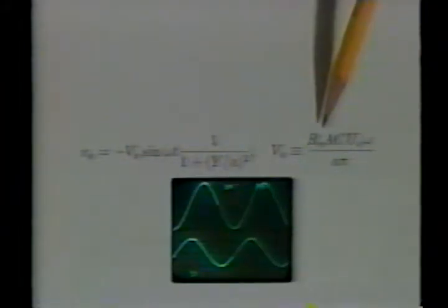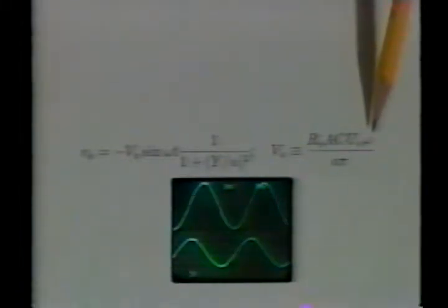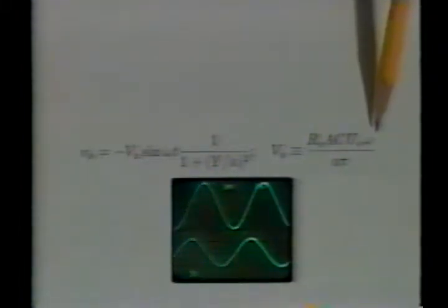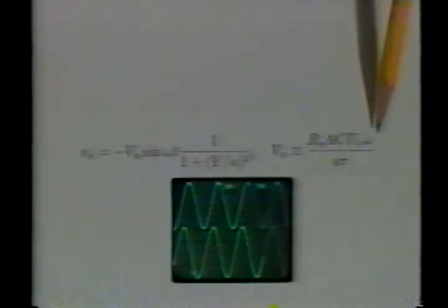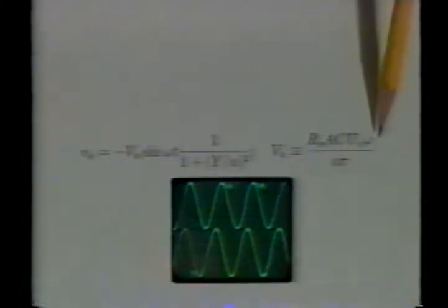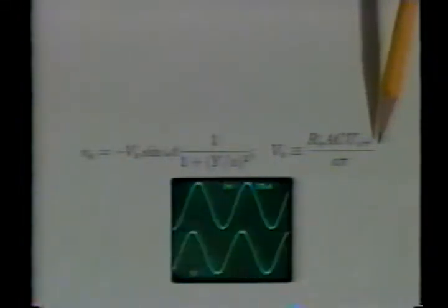But as the frequency is raised from 500 to 1000 Hertz, the probe signal saturates. As the frequency is raised to this range, the voltage of the probe becomes large enough that it does begin to influence the field distribution. Some of the field lines that originally terminated on the electrode are diverted to the grounded part of the plane.